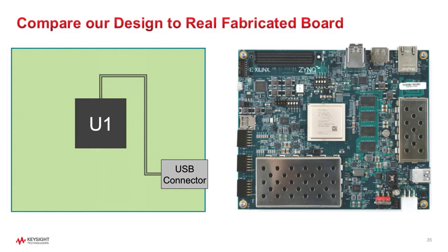Now that is a bit-by-bit mode, but for applications such as DDR5 or applications requiring really low bit error ratio, down to 1e to the minus 16, we have a statistical mode, where a stochastic process is started in the background. It's going to do the similar thing, and get you down to 1e to the minus 16. But to answer your question, yes, you can use your S parameter file to perform the channel simulation.